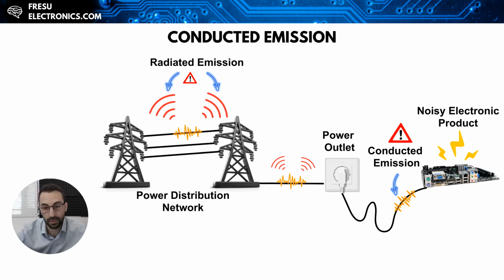And this is quite important because the structure of the power distribution system is built in a way that resembles a large antenna structure, which can then potentially radiate and upset many other systems that can be susceptible to that. To aggravate the issue, since the power distribution network is built with these longer cables, this also gives the possibility for large wavelengths to find a radiative structure and then potentially radiate.